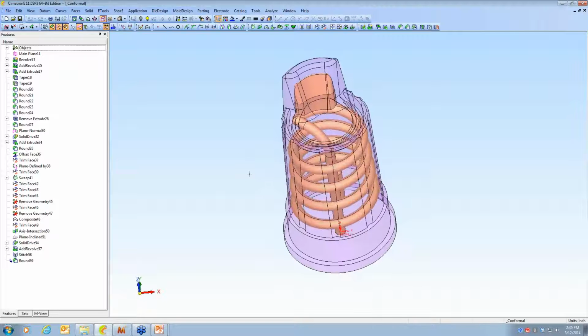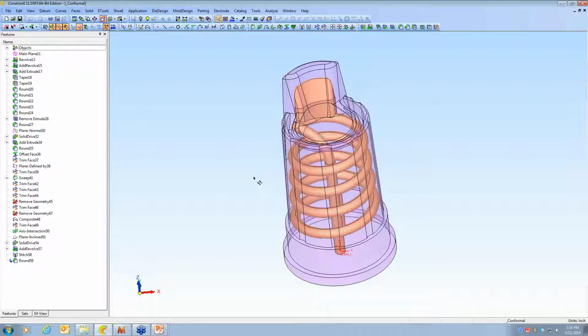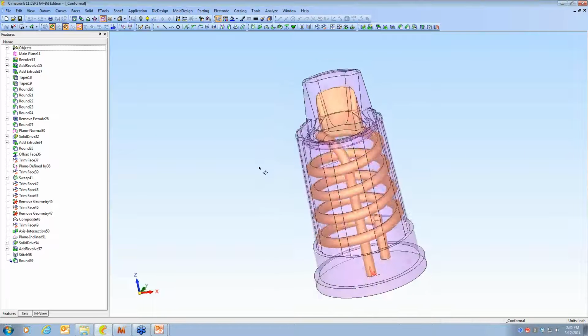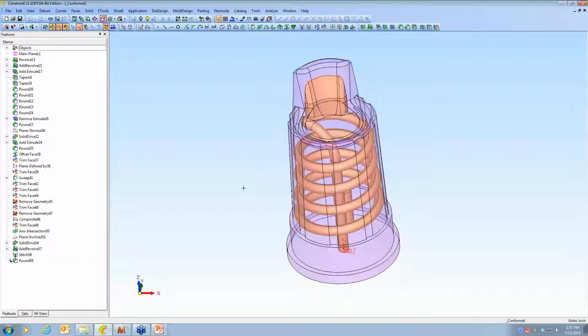Now, sometimes you can approximate a circuit like this by machining smaller inserts and laminating them together. But what has really made conformal cooling a topic of conversation lately are the new technologies for additive manufacturing. So what we generally now call 3D printing has been around for more than 20 years, and in that time the costs have come down and the tolerances have really gone up.